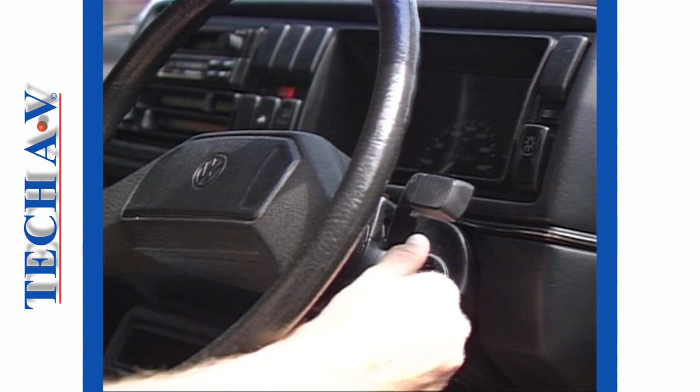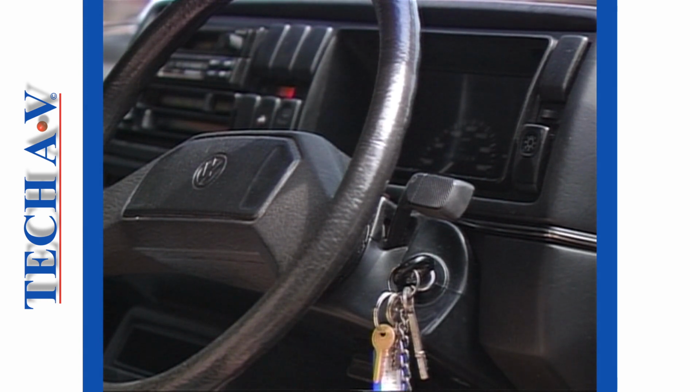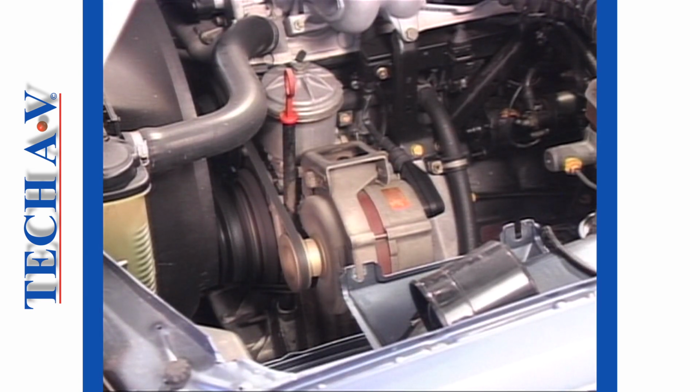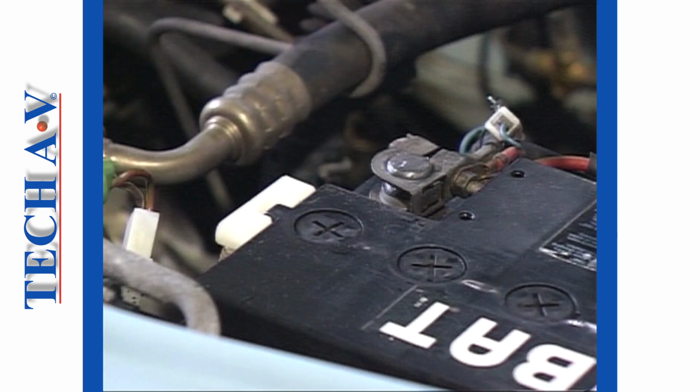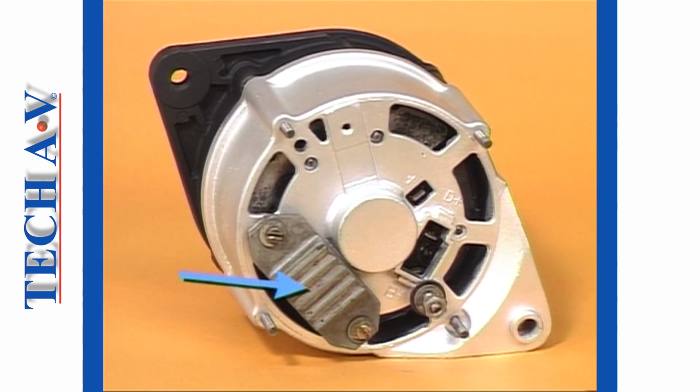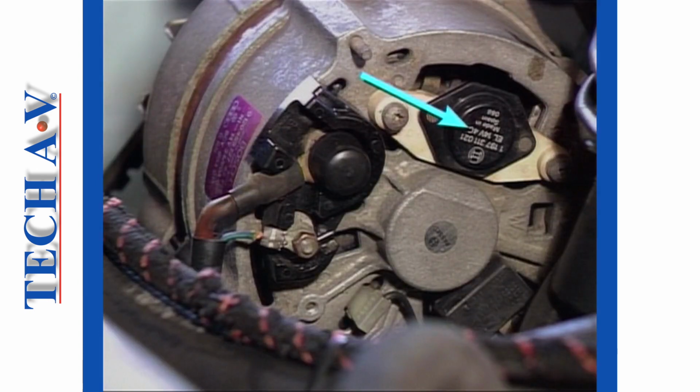The battery requires differing degrees of charge. For example, after a starter operation, it will need a lot of charge, and the alternator will deliver a high output. However, once nearly charged, the battery doesn't need much input from the alternator. To take care of this, a voltage regulator situated within the alternator is used. This device in effect regulates the strength of the field current and thereby increases or decreases the alternator output.